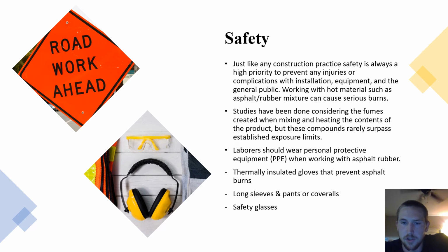Of course, laborers should wear personal protective equipment when working with asphalt rubber. This could include thermally insulated gloves, which could prevent burns, long sleeves and pants or coveralls, which help prevent burns as well, and of course, safety glasses.